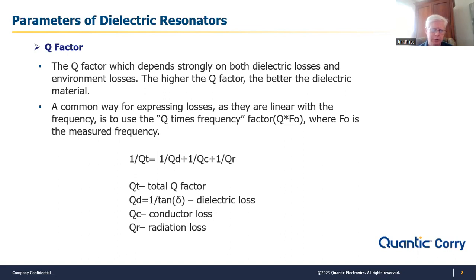But with the dielectric resonators, once you couple the energy into the resonator, it pretty much tends to stay there. It acts like a waveguide, and the wave pretty much stays inside the dielectric cavity itself, and just bounces back and forth from wall to wall inside the cavity, and doesn't tend to radiate much.